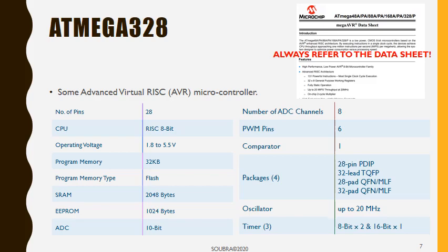Now, I'm going to give you more info about two things. First, I need to ask you one question. According to what we learned last year, when we power off a computer, what happens to the RAM? It's volatile, so basically disappears. So the RAM is volatile. The flash, it's not volatile. So whenever you upload some instructions in your program memory, even after power off, the program is still there. Not the data, the program. Two different memories. We're going to get to that.